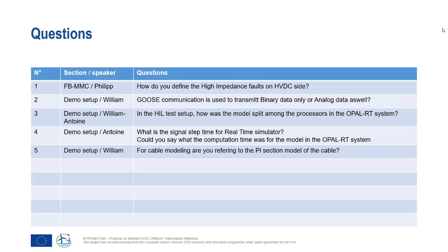But the answer for the question is, for GOOSE, you can only use it to transmit... No, sorry, I got confused. Binary data is just a type of data. Actually with GOOSE, you can transmit different types of data. I was confused because I was thinking of data meant to be states of breakers or tripping signals, but you can actually transmit integers or doubles or floats or any kind of data type. In the norm, there are different types of data defined for different kinds of purposes.